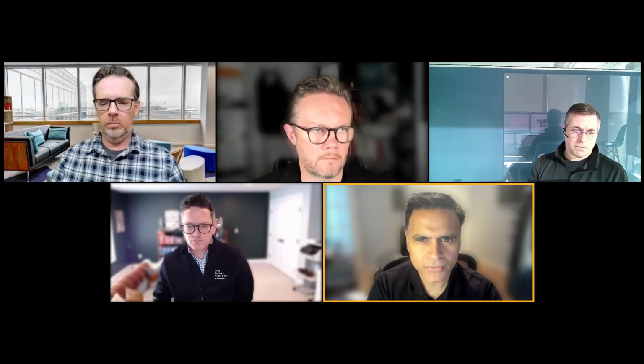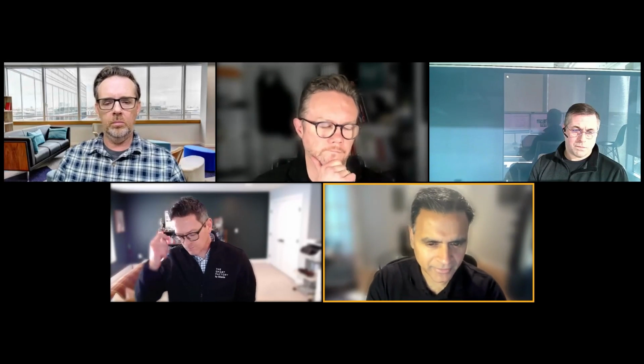Yeah, look, there's a lot of data formats that are available. Obviously on the factory floor, from machine to machine, you have OPC UA, you have Modbus, various other formats. But when it comes to bringing the data to the enterprise, you need something that's lightweight, that's event-driven, that is publish subscribe. So to optimize your bandwidth, which is already limited, and connectivity, which is somewhat limited because you want to use your core connectivity for your factory operations and not tax that with moving data. And so that's why I think MQTT as a protocol is becoming pretty popular and almost a de facto standard